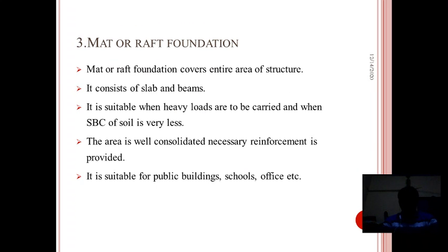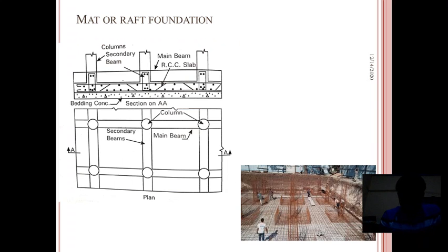So this increases the load bearing capacity and reduces the pressure intensity, and it is suitable for public buildings, schools, offices, etc. This is one of the important advantages of mat or raft foundation, to reduce the intensity of pressure and to have higher load carrying capacity. So this is the figure in question.